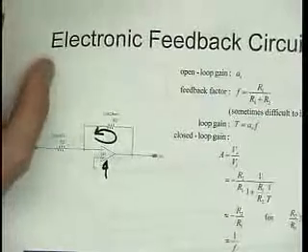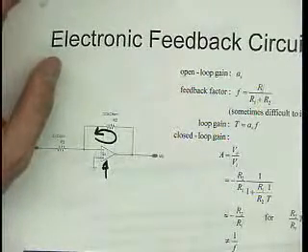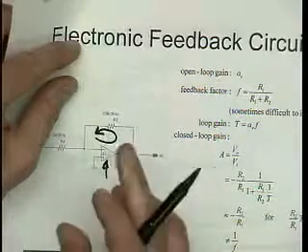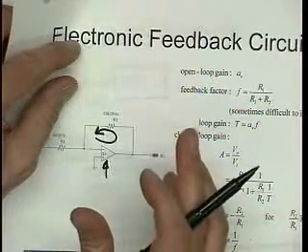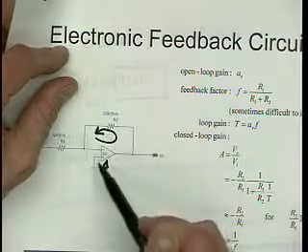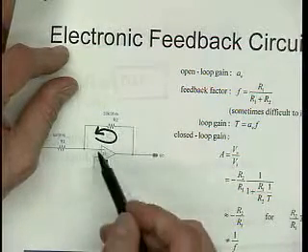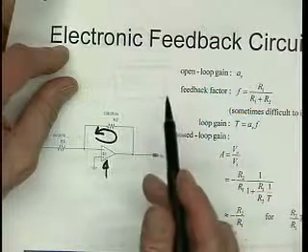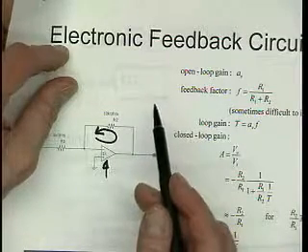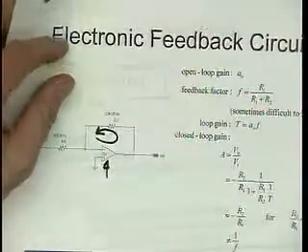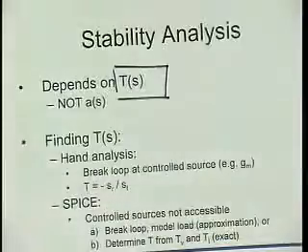Of course, that is part of T of S. But by just knowing this gain here, we cannot really be sure whether the amplifier is stable or not. I mean, we could actually have a circuit that is unstable if we just were to put unity gain feedback around just this part. But if we use just the right feedback network, it becomes stable. And then, of course, more often the other way around also.